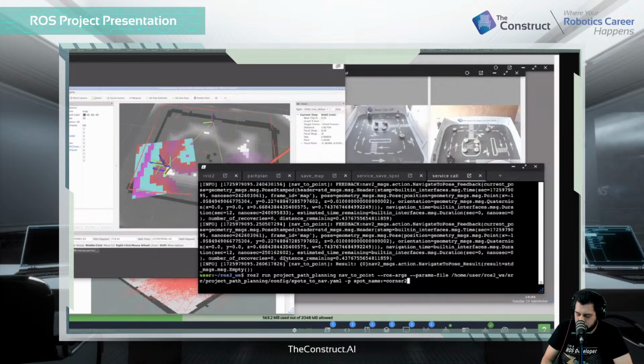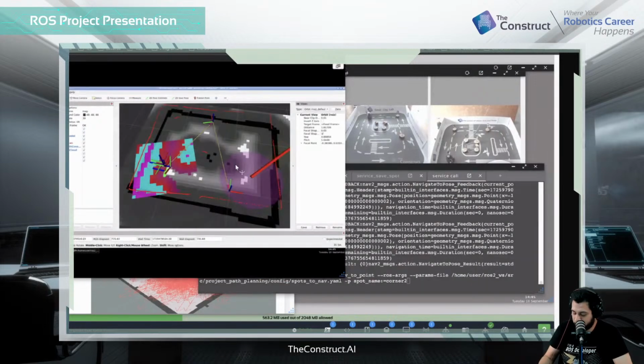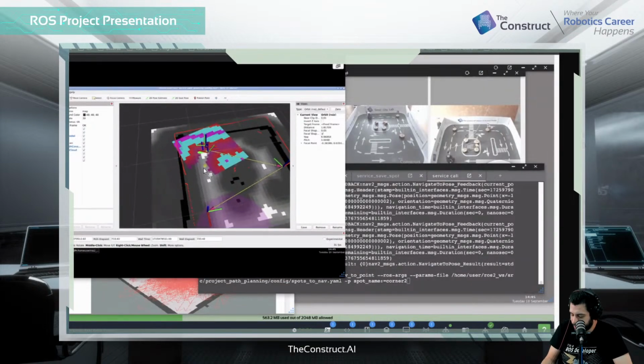Yeah, that's to use the Gazebo clock versus the real clock. But basically you're taking care of checking that the inflation radius is not too big and that your footprint corresponds to the robot. Just doing maintenance on that. I'm surprised it worked right out of the gate, and I'm glad.